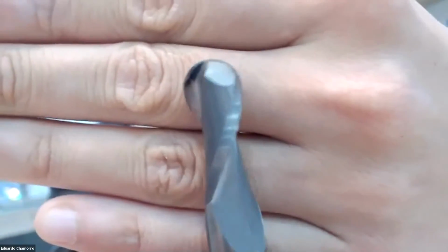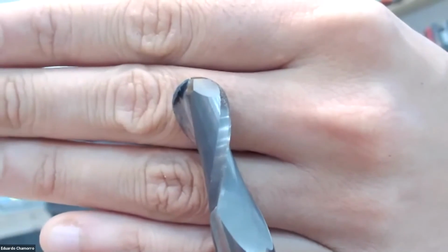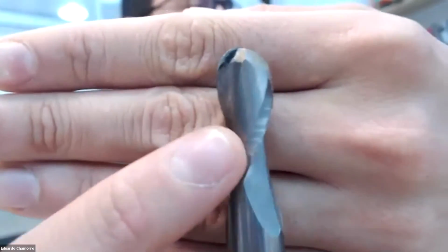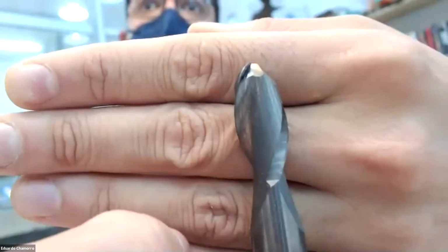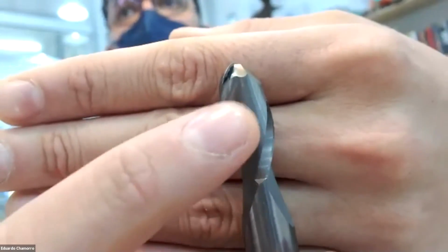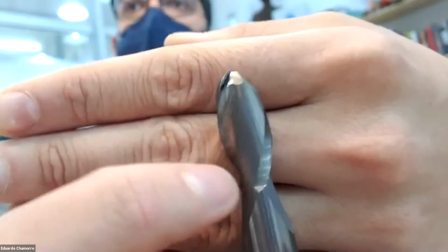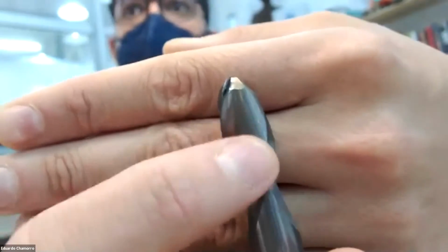This, for example, is a two flute, two flute round point. This is for finishing or three-dimensional cuts. You can see that we have one flute here and one flute on the other side, but the space on the back of the flute is smooth. This is not a flute. In general, round cutters don't have a flute. It's a weird example, but if it was a flute, instead of a shiny surface we would see little engraved marks that are like mini flutes.